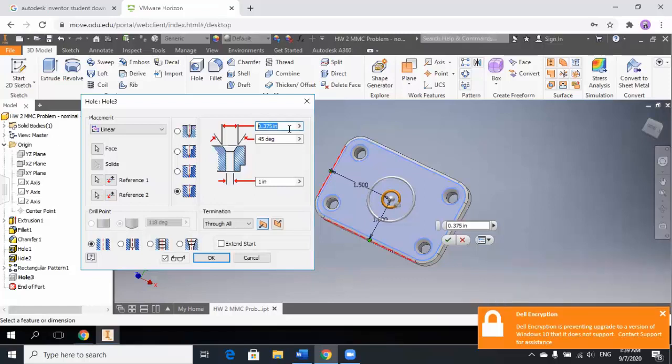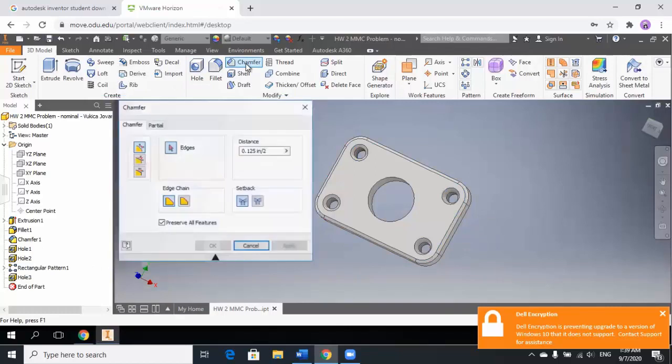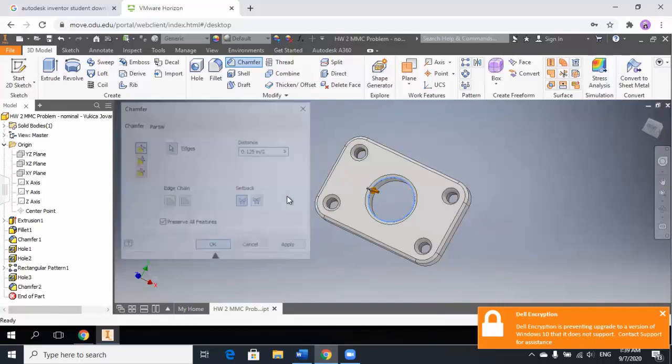And then that will be, so let's see how that works. Or smaller chamfer, I think 0.125 divided by 2, that will be my chamfer here. Let's see if it can calculate it. No. 0.125. Okay, I won't do it like that. I will just add chamfer, same chamfer that I had here, and that's it.